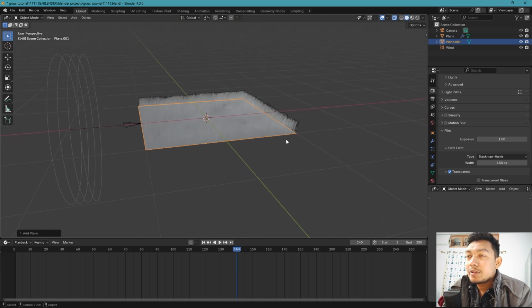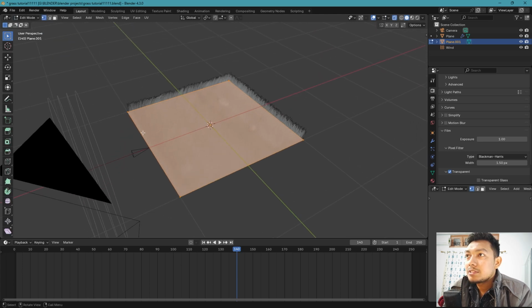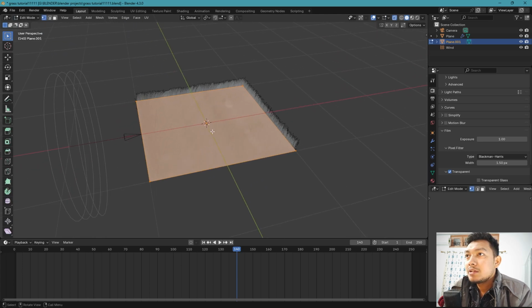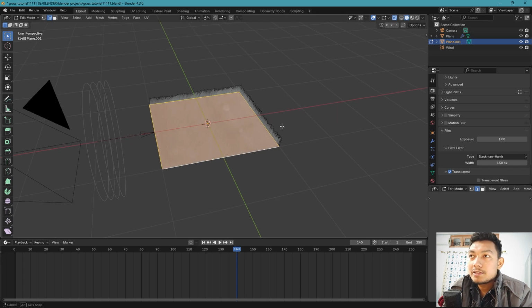Let's click the plane, it's already selected, and come to edit mode, and you can see these vertices, edges, faces. So I'll press 2. If you press 2, you'll come to edge selection. If you press 3, it's face selection. If 1, or you can hover your mouse over here and click on it. You can select from here. 1 to 3 is the shortcut. I press one of the edges by holding Alt, so all the edges will be selected.